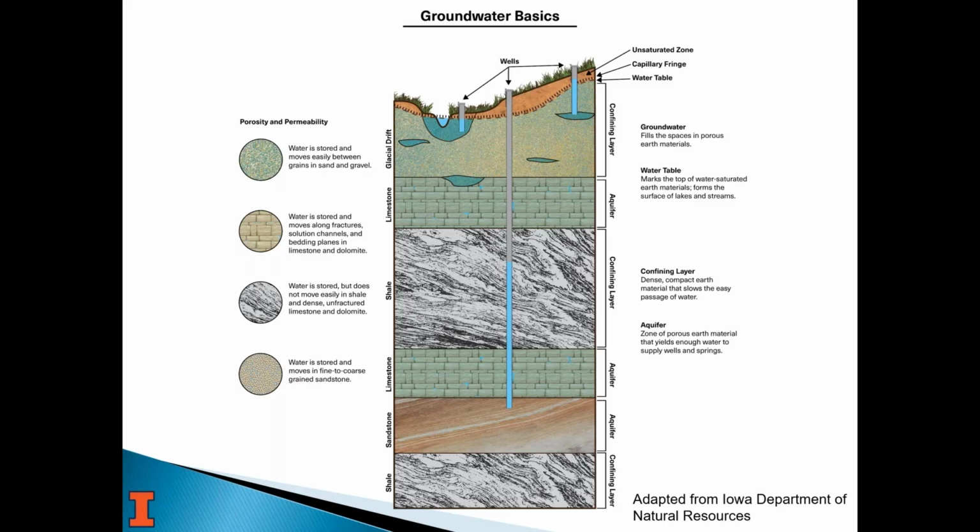And so that aquifer, the well that's at the top on the farthest right, that little half moon shaped aquifer could be 20 miles long and 50 feet thick. And I mean, that's a pretty good water supply, especially for a home well. There's also a water table in that shallow soil environment that's totally separate from an aquifer, or can be. Near the river, it's the same. Where that buried sand and gravel is, it's different.